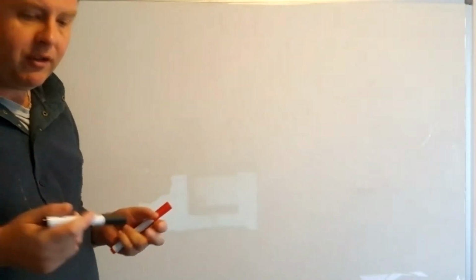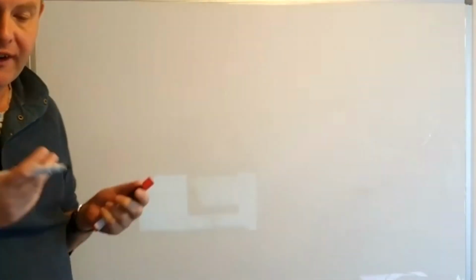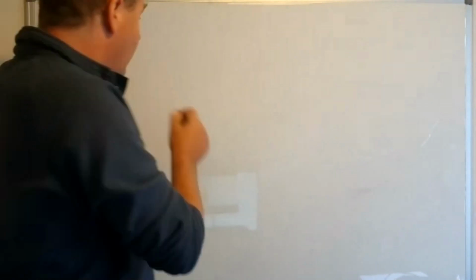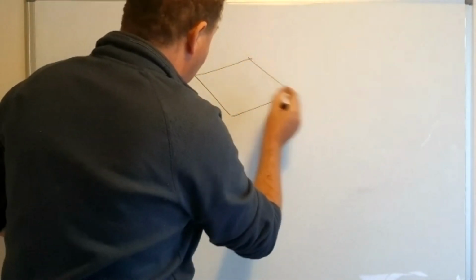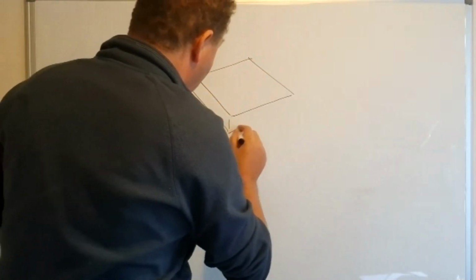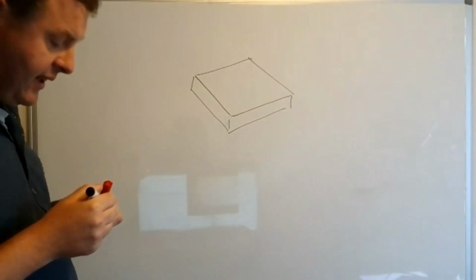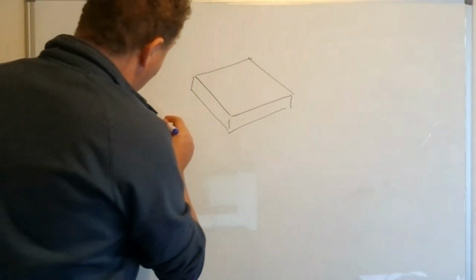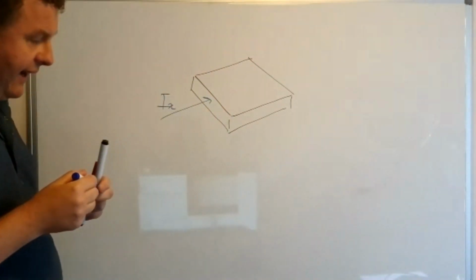Okay, so I thought I'd start by looking at, for example, how a Hall sensor works. This is stuff that you will probably have covered with Professor Marrows in last year's Physics 4 solid state lectures. So we start with a square of conductor, and we're going to apply an electrical current, which we'll call I_x.